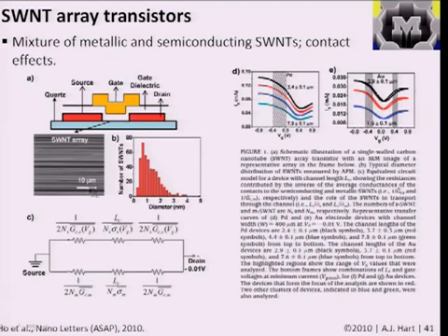So the tubes are, as you can see from the comparison to the previous work, definitely longer than the ballistic transport length. And in the case of the semiconducting tubes, we have the same scaling with respect to the length and the number, but the conductivity of the semiconducting tube, sigma sub s, depends on the gate voltage, V sub g, or how much external potential is being applied to modulate the conductivity of the semiconducting tubes. And these are the characteristics of the devices, which we won't get into now.